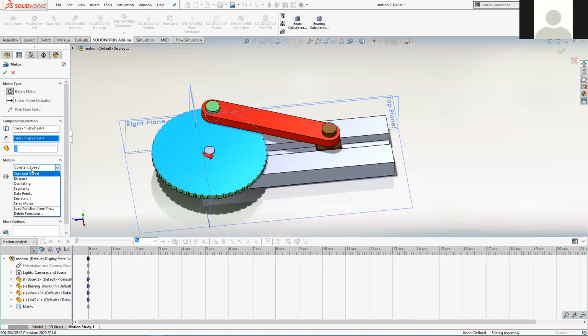So that's what we're going to do. Rather than constant speed, which is a very basic way of setting this up, we want to chop the time of the simulation into little segments, and set what the velocity is at any given segment so that it will ramp in and possibly ramp back out again in a more controlled manner.